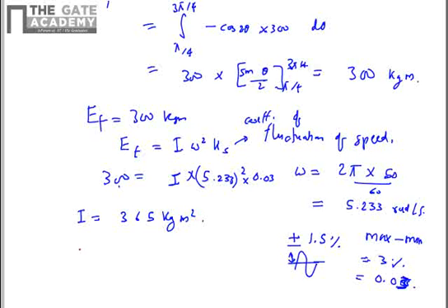Now we have to calculate the moment of inertia of the flywheel. So we have the moment of inertia of the existing component. The existing component is given as I existing, that can be derived from a mass of 450 divided by g, concentrated at 1 meter of radius of gyration that was given in the problem.